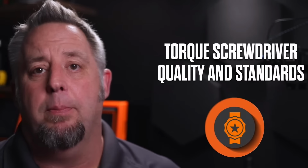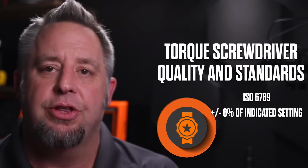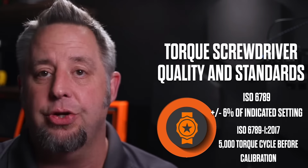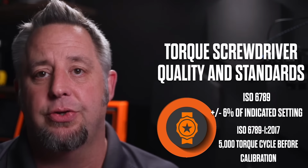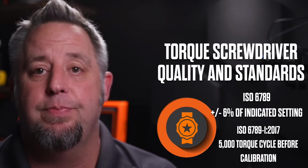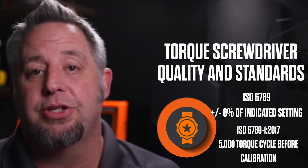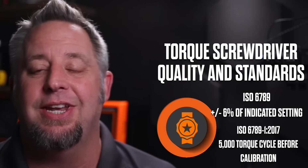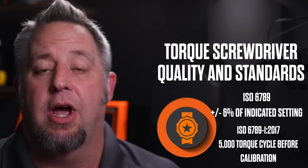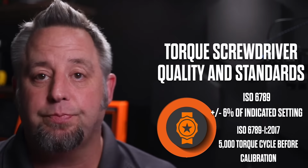When we look at torque screwdrivers, one of the quality standards that goes along with their use is ISO 6789. As it relates to torque screwdrivers, those have a value of plus or minus 6% of the indicated setting for the repeatability of those tools to qualify as an ISO 6789 tool.